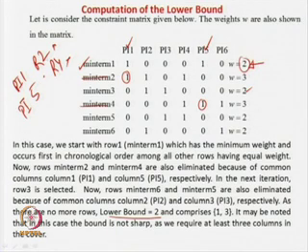But if you do this, then again you are doing a tree, like an if-then-else question: if I cover minterm 1 by Pi 1, then you remove row 2, or if I do it by Pi 5, then you remove row 4. Then the heuristic and again a tree comes into the picture. But we do not want to do that. What do we want? We want to go for a very quick solution. So, in this case we say that it will be covered either by Pi 1 or Pi 5, but not both.